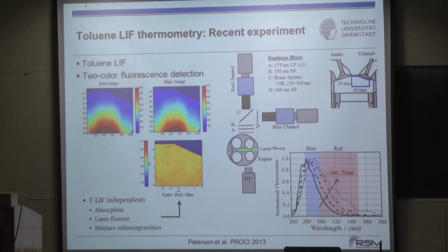Okay. Yes, please. You have mentioned that it can be measured only in motoring. If I am looking for a diffusion flame, this will not be useful for motoring, because there will be no fuel injected. Right. Then what is the use? For diffusion flames, we use either Raman Rayleigh spectroscopy or CARS. Then if I use an endoscope instead of spectroscopy?